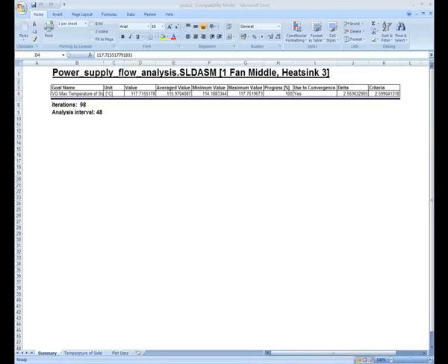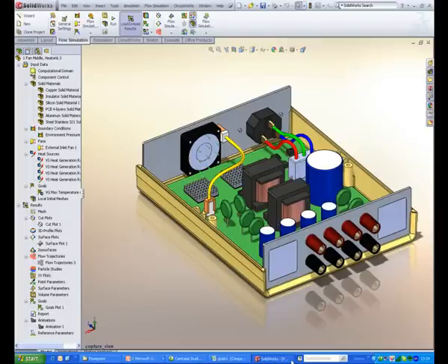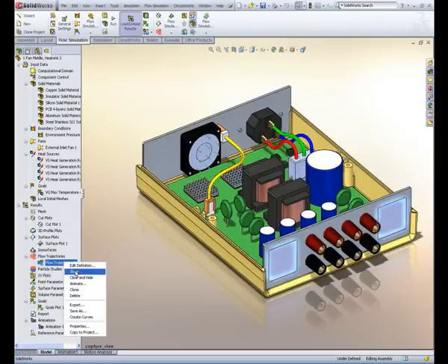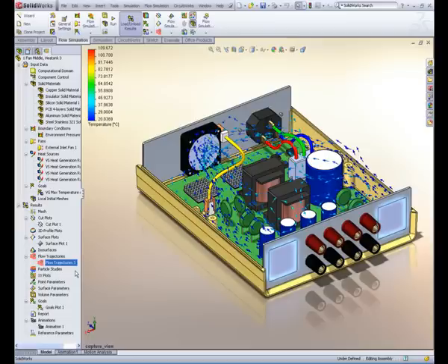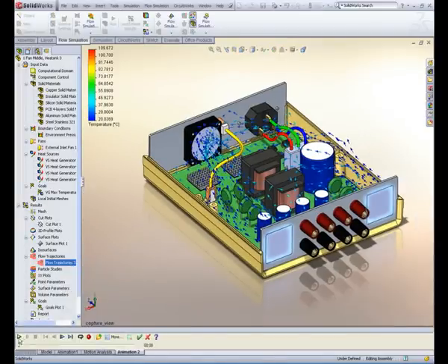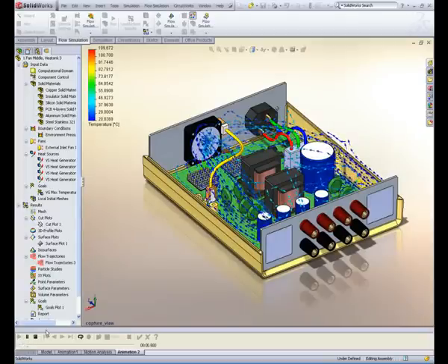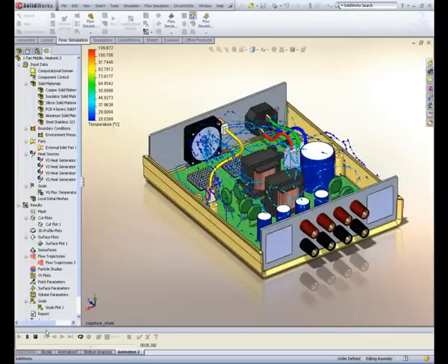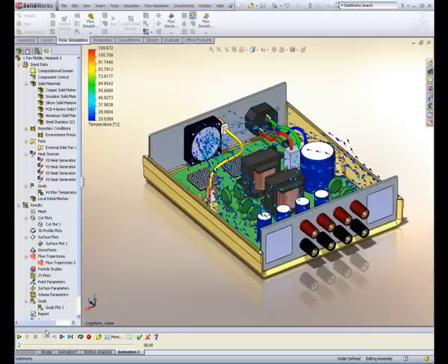We can also use SolidWorks Flow Simulation to demonstrate the flow trajectories, which will indicate how the air is drawn across the enclosure, cooling the various components along the way. Typically, this aids us in placing the various parts to obtain the maximum cooling effect, and is often helpful in indicating areas of flow recirculation or stagnation in systems.